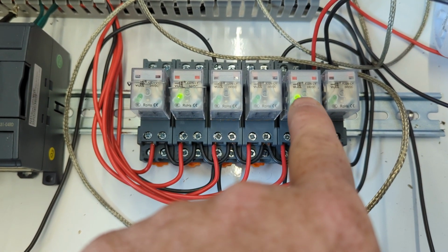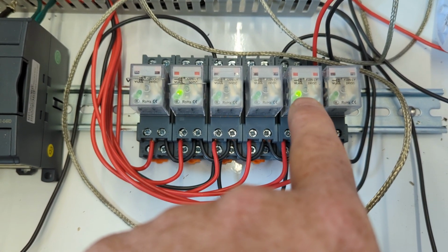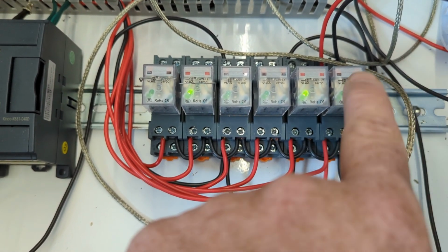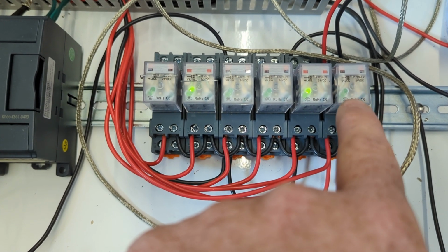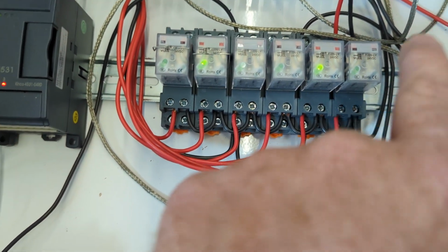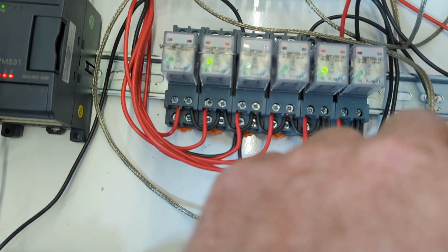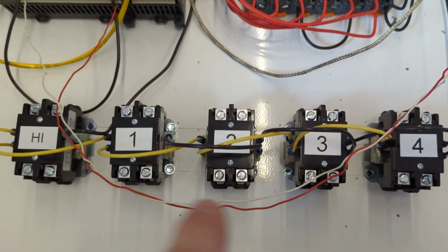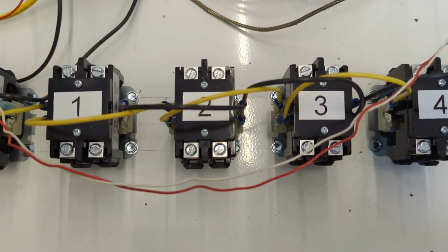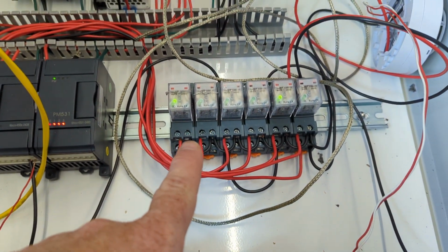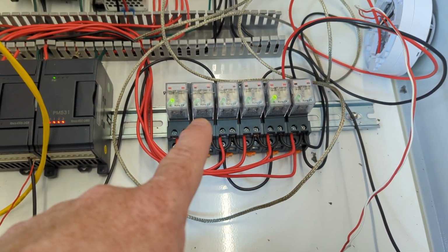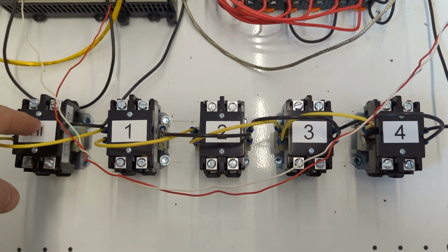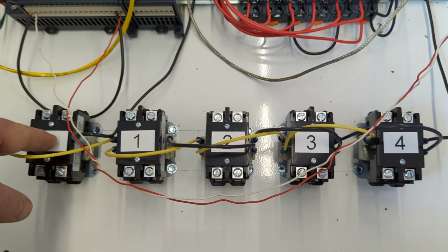This relay is the relay that turns on and off the miners, and then this relay cycles power to the smoke detector if required, or after a smoke event, that power has to go off for the smoke detector to reset. And then down here, these are our mainline contactors. These relays are capable of doing up to 10 amps. And these relays are capable of doing 40 amps. So this one controls the high-speed fan because it uses the most power.